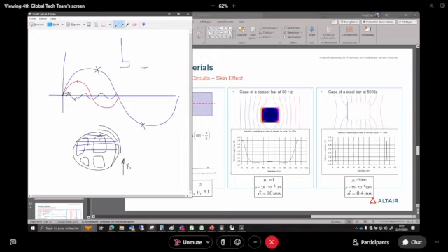Actually, in the coils, you will have copper wires. If you have a big diameter, then you are going to use copper for nothing, because for high frequency you will have this skin effect. And unfortunately, there is another phenomenon called the proximity effect. Finally, the same wires will have this eddy current like this, unfortunately, due to the proximity effect.